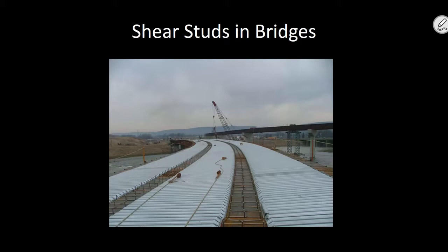In bridges, we have this issue of fatigue that we need to deal with. We just talked about it, right? Well, a shear stud, I propose, is the potential introduction of a flaw. You are welding a shear stud to the top flange. That creates a potential issue with fatigue. So hence in bridges, there's studs everywhere, okay? Make sense?